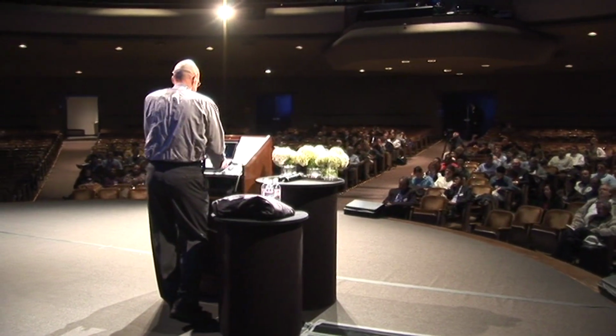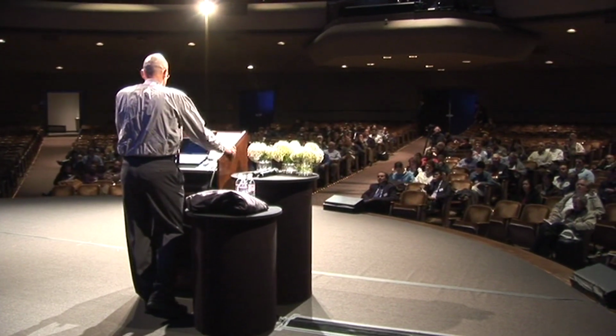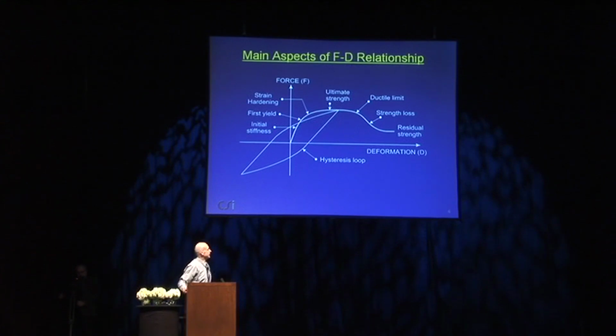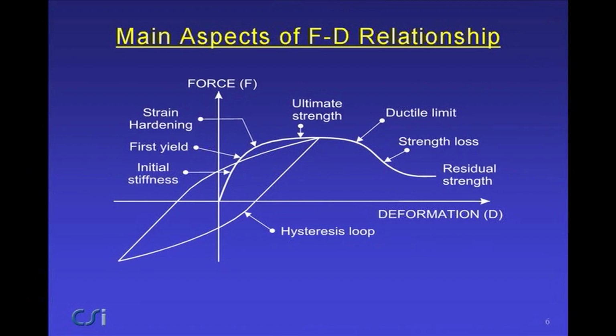And one of the things I'll emphasize is that for seismic analysis, P-delta theory is perfectly adequate. You almost never, and probably never, need to do large displacements analysis, and if you do, you're simply wasting computer time. The material nonlinearity is the more complicated of the two, and that's which I'll give most attention to in this session.